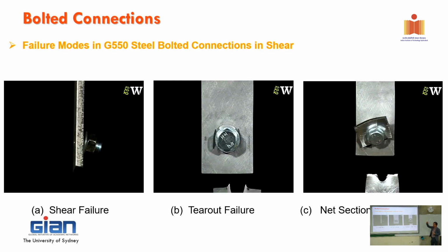We don't have lip, depending on the company. Some companies, like Endo Frame from Australia, they have plain section, no lip. Yeah. So it's a little bit weak. So we do a couple of tests now and see whether it's a good idea or they need to fold the lip in here. But the lip is very complicated in this case because right in here, at the connection, you have to cut the lip to fit that one in. So it's going to be a little bit tricky, right? When you go up here, you have to cut the lip, and then you fit that one in, and then you screw it in here. That's how it works in practice. All right. So on the detail, it's a little bit more complicated than we thought. But the thing about that, I do it.